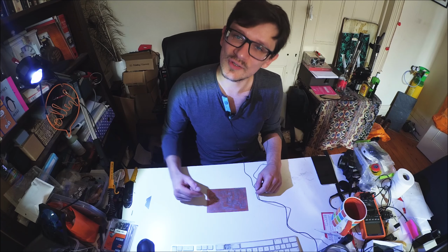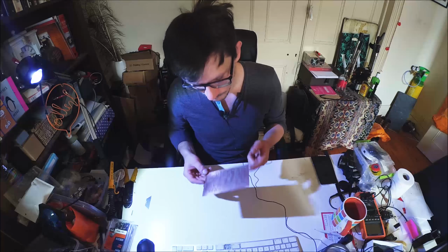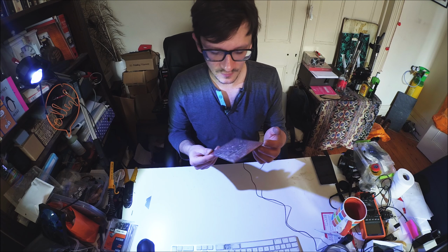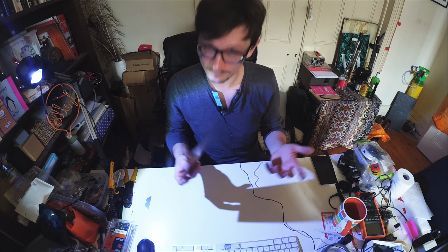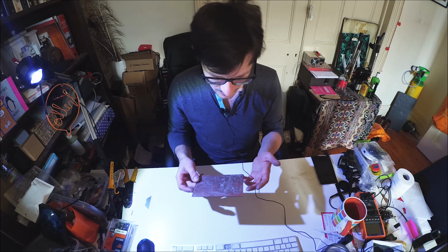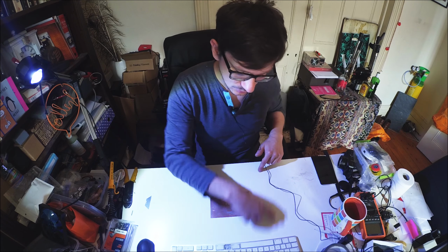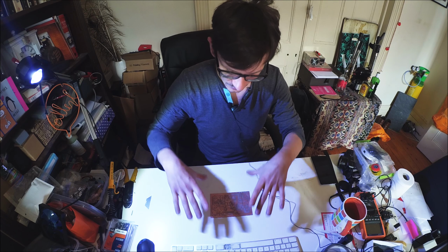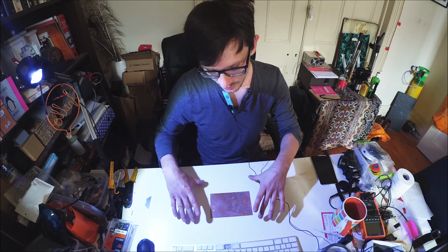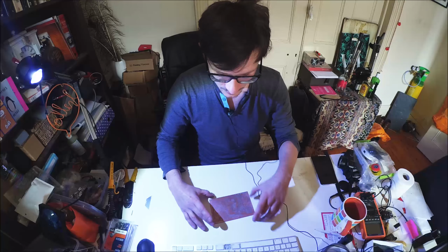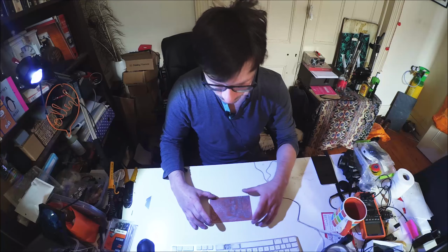So the CNC process is complete, and the board looks great. The way I did it is probably not the right way, but one of many ways to do it: securing the copper clad board to the bed of my machine with nails or screws or whatever, and then doing the top layer, the holes, and the cutout.